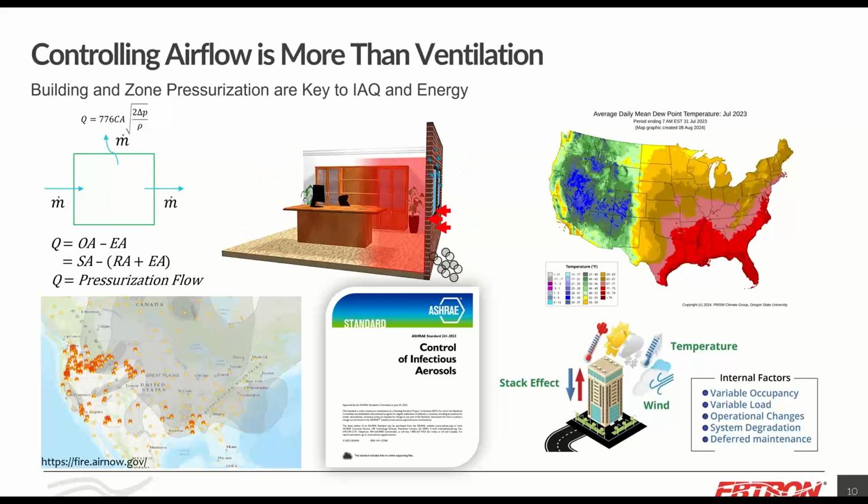And of course, buildings themselves are dynamic. HVAC systems within buildings can fight each other. The higher the number of floors, the more the stack effect. You can have stack effect with as few as four floors. Everybody that has a chimney on the house can see stack effect in action all the time, depending upon the outside air temperature, and then you have wind pressure outside. A lot of dynamic things are always happening. Because of energy savings, most of our systems are dynamic. Most fans, even if they're constant volume, have multiple speeds and are always having an effect on the pressure of the building and the ventilation rate into the building.